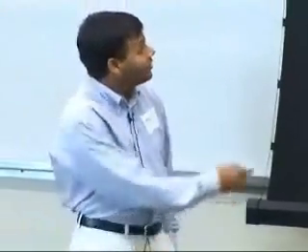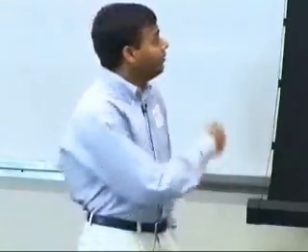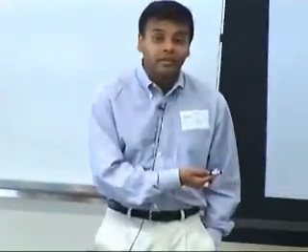And to be able to do analysis of single event multiple upsets, you have to worry about layout, you have to worry about technology CAD. And we are doing some work, and we think that the BISER can cut down even single event multiple upsets by more than 100x. Actually, it could be up to 300x. Because to give you the heuristic explanation of why that would be the case, in BISER, first of all, the corresponding nodes only have to be upset to be able to create a problem.